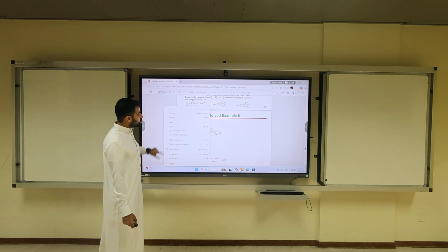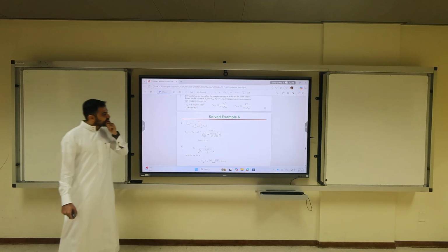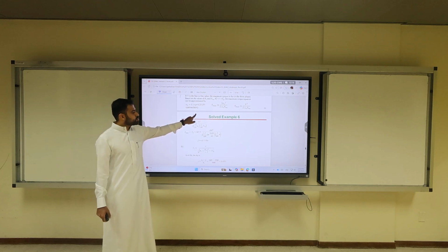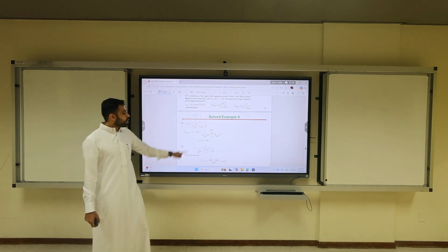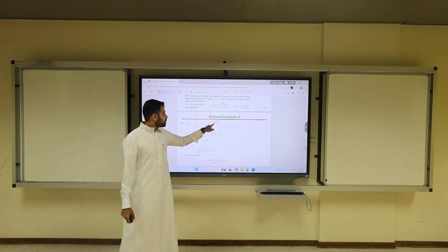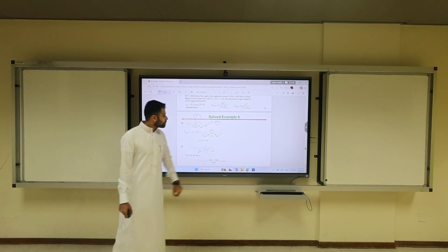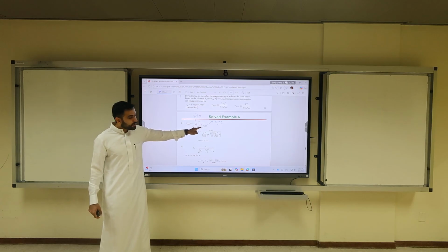So what he's doing here is he is asked to calculate the frequency. What is happening here? What is omega S? It's 2 pi over 60 ns, right? Yes. What is X equivalent? It is j 2 pi F, or we call it omega electrical. This is electrical. This is mechanical, because impedance is electrical. Speed is mechanical. And this is L. So what he is doing here is he is multiplying by F, dividing by 60.